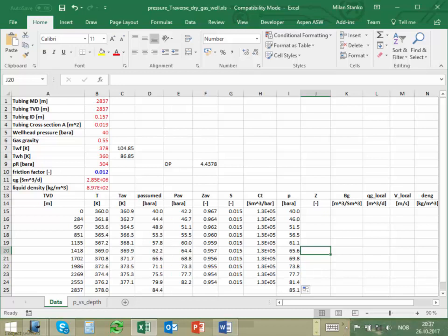Okay, and you see, if I do it like that in parts, I actually found a slightly different value than using it in one segment. Why? Because remember, the tubing equation assumes that the properties don't change much. But when I discretize, there is some variation and I'm capturing the delta P much better. But you see, the difference practically is not very much. Okay, so that's the homework.